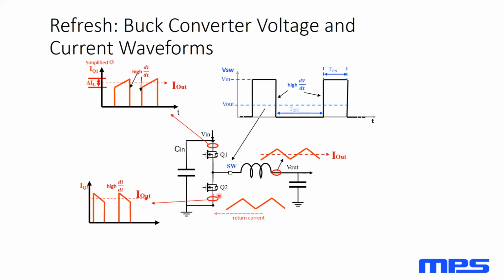The return current, we want to pretty much be a mirror. And if we have the exact opposite, so to speak, current from I out of the converter on the return current, we're going to be in pretty good shape as long as that loop is small.